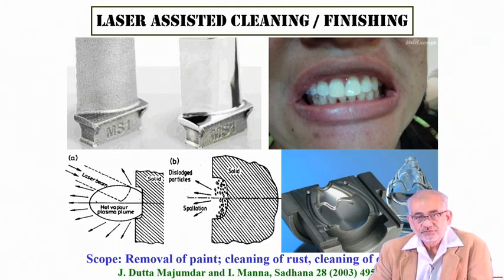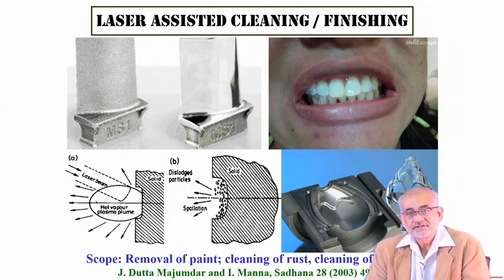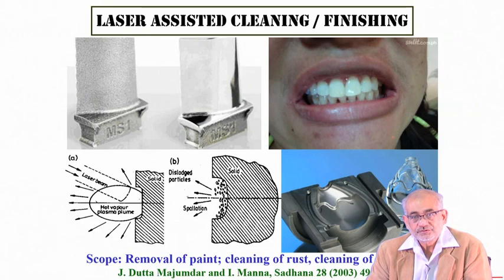So you have to remove those complex compound layers, and you can't even use a soap solution because that will react and make a different kind of color. So the only way is to remove the oxide layer or the reaction layer from the surface by way of vaporization. And laser can do that very, very precisely. So indeed, laser is used for cleaning priceless art objects.